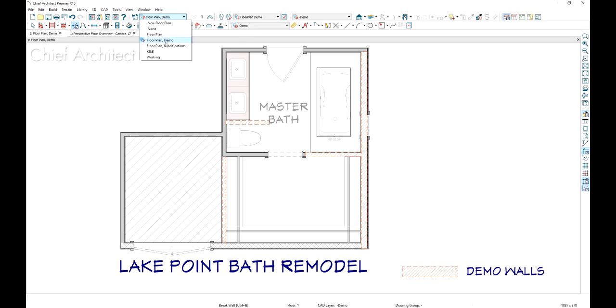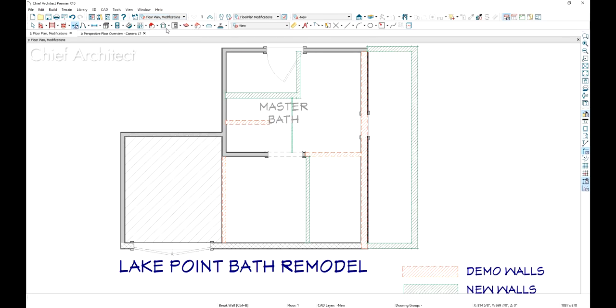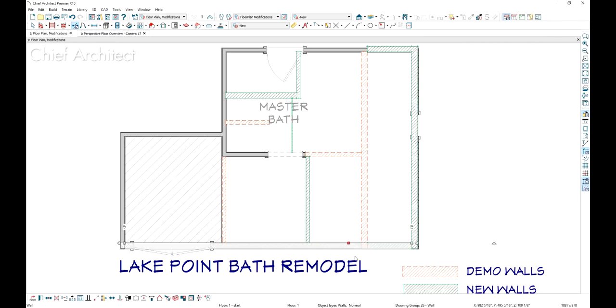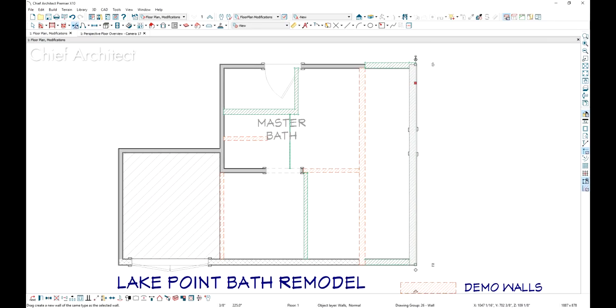Let's turn on the plan modifications for the walls that we need to add. Now notice that I didn't actually delete the wall that's underneath of this one because I'm actually going to just slide that out because it's an exterior wall. We'll snap that into place. That should have extended this wall down here. And then on the upper portion of that wall, let's use this diamond, and we'll just pull it back. Make sure that we snap that into place.